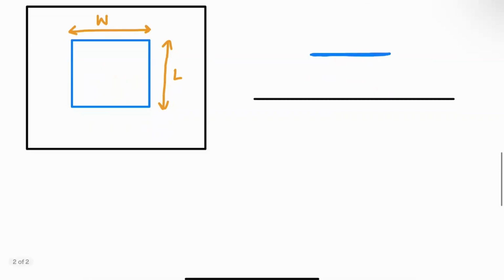So we know that, so I'm just going to erase this to make some space. So we know that, if I have, this is my patch metal, we know that current has to be zero at this point and this point, right, from the boundary condition. You can't have a current flowing into air. So if it's a half wavelength patch or approximately half wavelength patch, then the current has to be maximum in the middle and zero on the ends. So sinusoid like that.